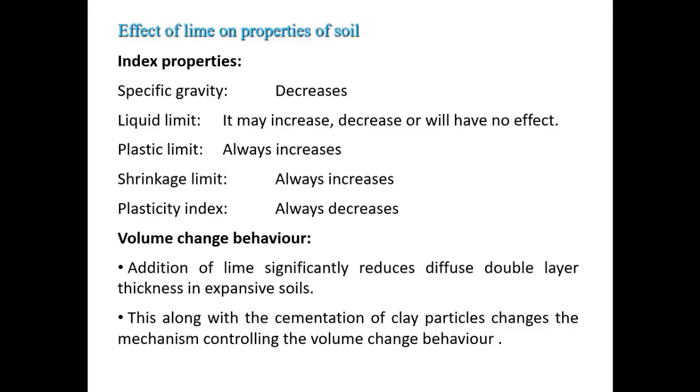Effect on volume change behavior. With the addition of lime, the diffuse double layer thickness in expansive soil decreases and the consequent cementation of particles takes place. This causes binding of soil particles and reduction in swell and shrink behavior.